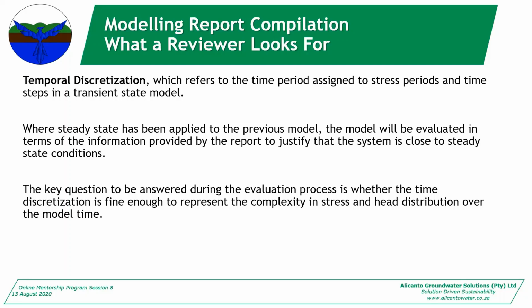Then in terms of your aquifers, that's going to come down to your spatial discretization. If you say your unconfined aquifer overlays the confined aquifer, you need to make sure that you've got at least 3 layers. One for the unconfined aquifer, one for the confining layer or the aquitard in between them, and then one for the confined aquifer. So that would come down to your spatial discretization.